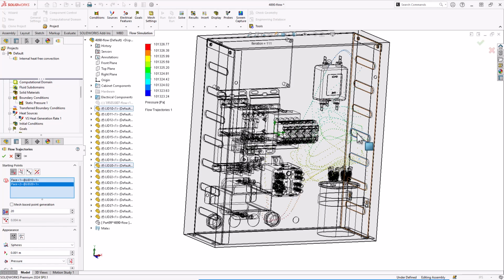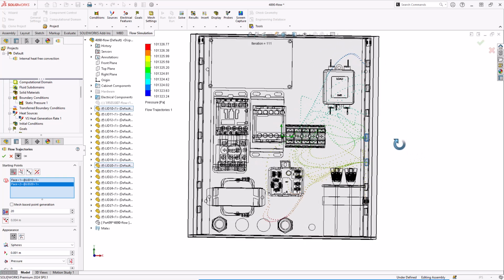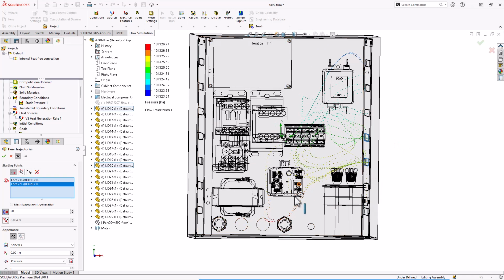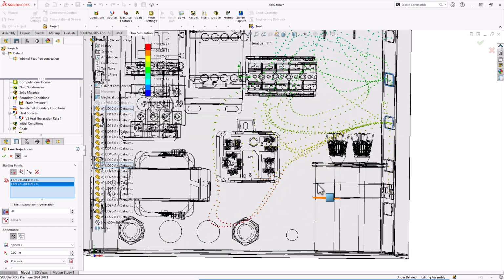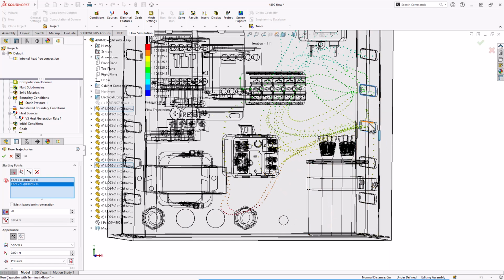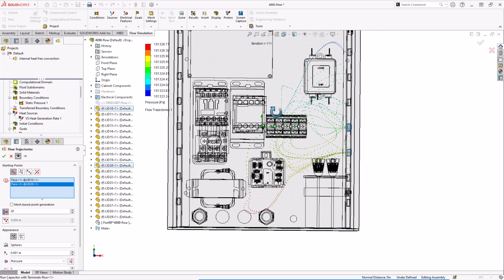And this is something I'll show you that illustrates some problems people often get. They'll click the inlet or the outlet and they'll get this movement, and then they realize, hey, what's going on down here? It's completely empty. If you ever see an empty area, all that means is the bulk of the airflow that you picked does not end up down there. The bulk of the airflow does not go there, it goes somewhere else. Does that mean there's no air down there? Of course not. So what you've got to do is decide, okay, what do I really want?